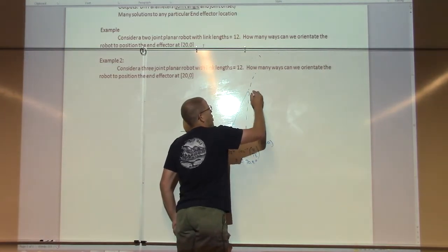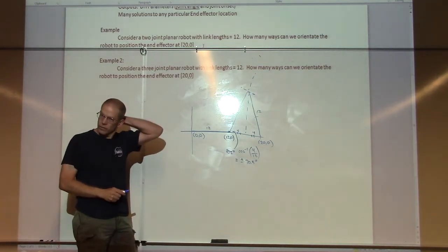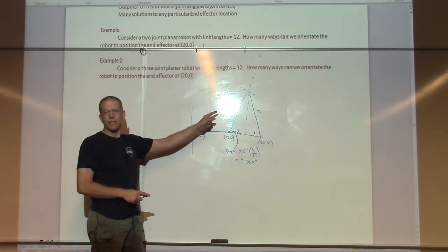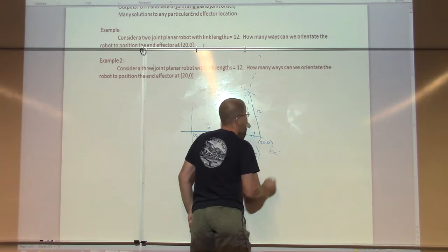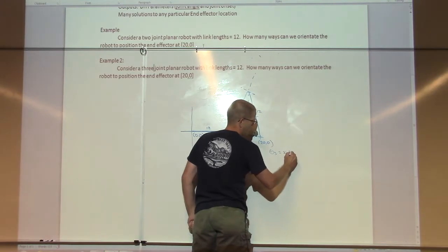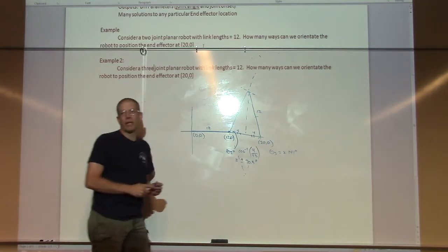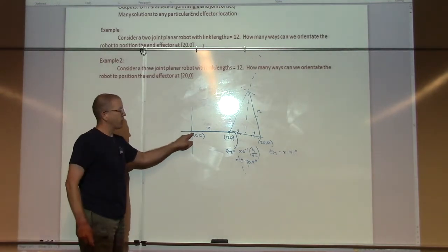And then what would our theta 3 end up being? Again, it would be twice that, pointed in the other direction. So our theta 3 then would be 141 degrees, so minus or plus 141 degrees. Because we know that, just like before, we have a second possible solution given this initial base angle of 0. Okay. Now what happens if we decide to pick something other than 0 for our initial angle?